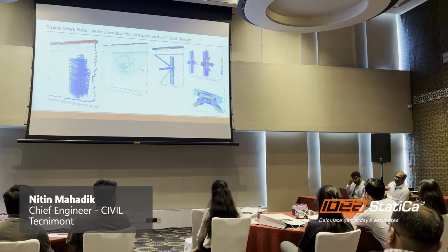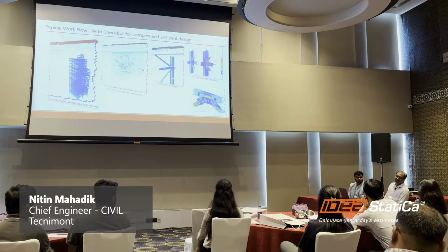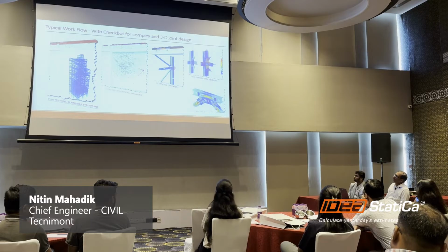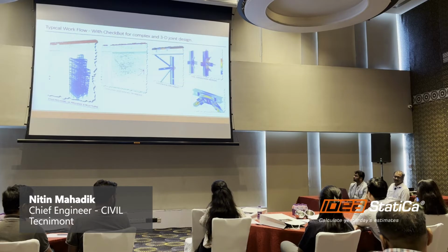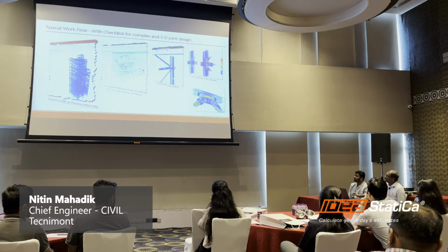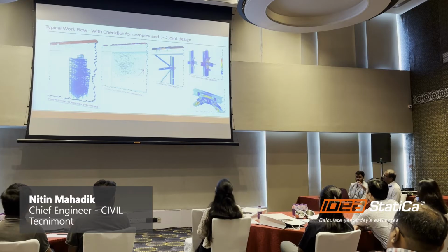One question which I heard is that there are many load combinations. We have thousands, more than thousands of load combinations, and we import them in IDEA StatiCa. One thing I just wanted to tell you is that you have to have a fast processor, maybe 16 GB, and from version 24, I think, they have introduced critical load combinations. They can discard all the non-critical load combinations and only use the critical ones. So it is comparatively fast. So this is a workflow which we normally use.